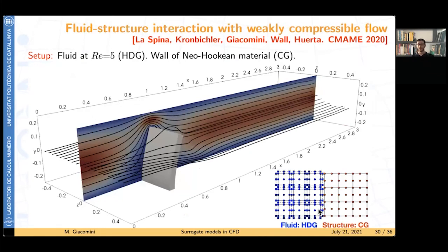But remember that I've talked about incompressible flows early on. So we are interested in seeing whether we are able to perform incompressible simulation also in high order. And this is indeed a collaboration with the group of Van Waal at TU Munich, in which we perform simulation of fluid structure interaction where the fluid was modeled using weakly compressible flows. So Reynolds number here is very small. This was not the goal of going high order, high in the Reynolds number. The goal was about compressibility.